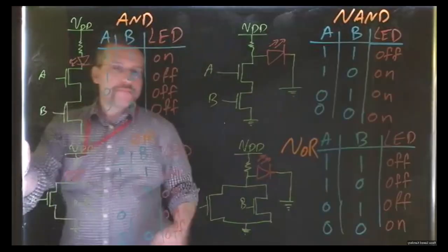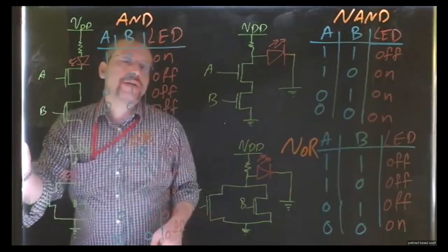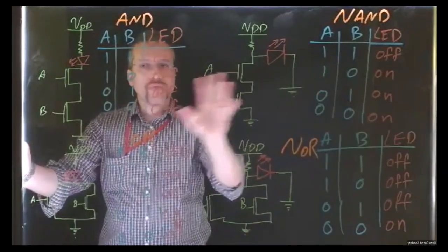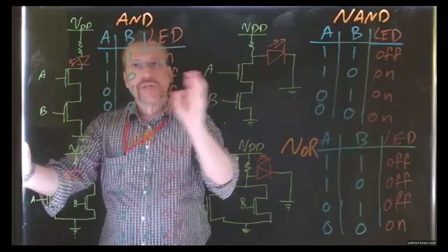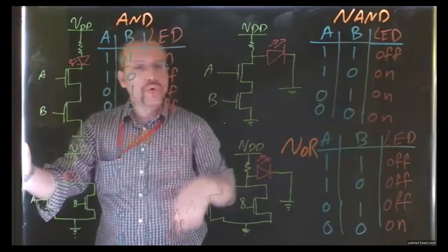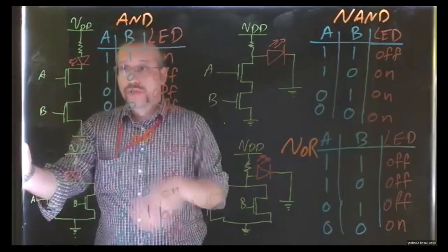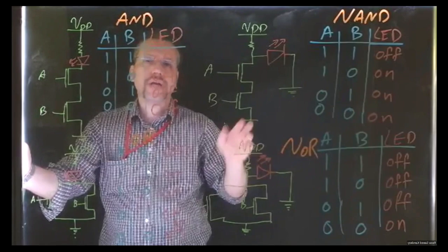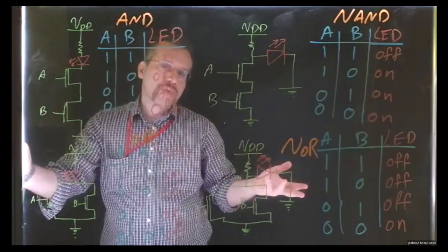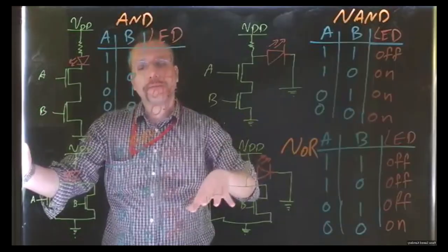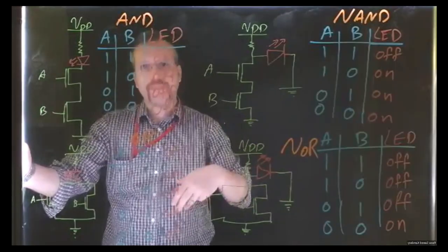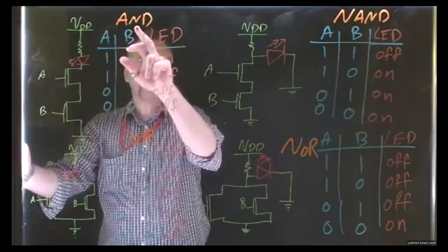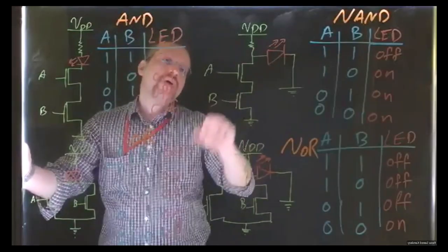So this is the way that the main logic circuits are going to work, and we can build those logic circuits, the AND, OR, NAND, and NOR, using two MOSFETs. In this case, we use NMOS. There are more complicated topologies where they use a combination of NMOS and PMOS, or there are some other logic gates besides AND, OR, NAND, and NOR.